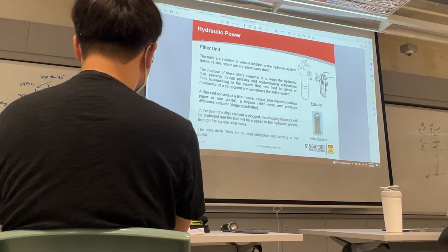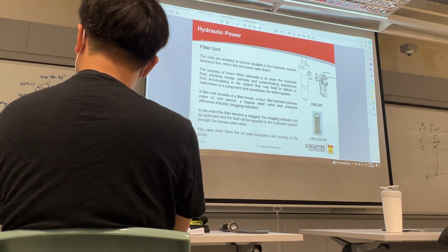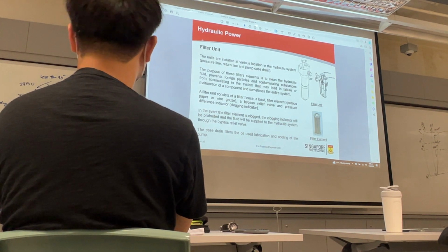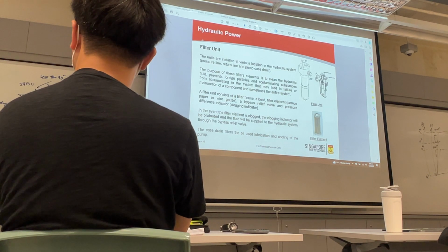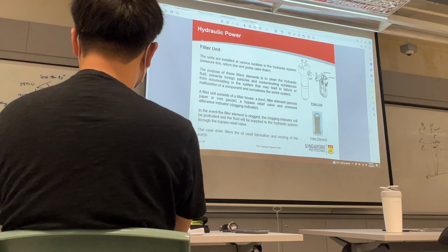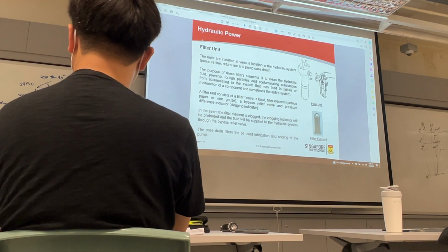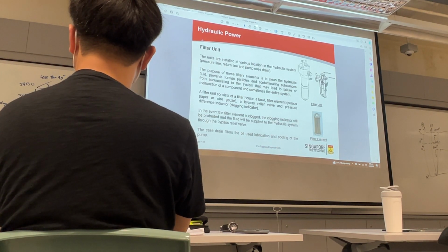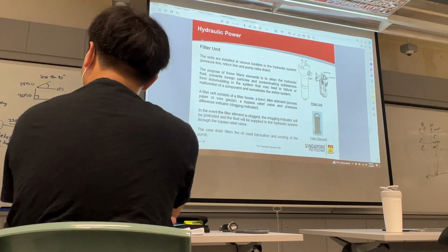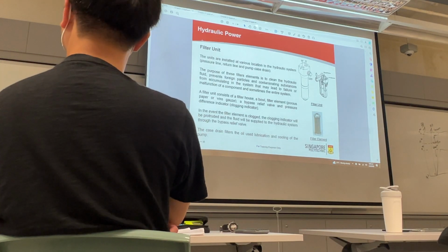If it's clogged in flight, 17 hours, you're 10 hours in, now you're in the Pacific Ocean, then what do you do? Turn back? Eject? Cannot. I have to allow the contaminated fluid to go into my actuator. No choice. But once it lands, the ground crew must check this indicator. This indicator is red in color. It pops out, you check, it pops out. Then you better go and investigate. Don't reset. If you reset, that means you're blur. Cannot. If you reset, you tell me.